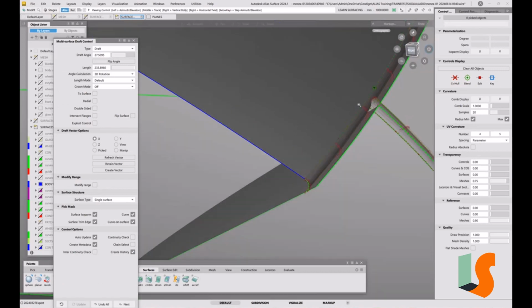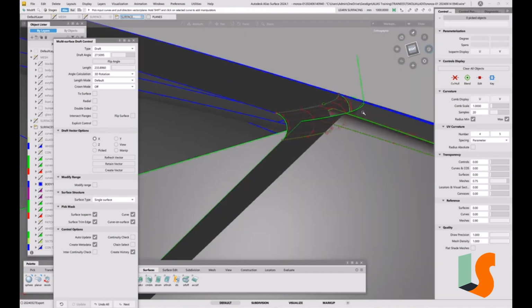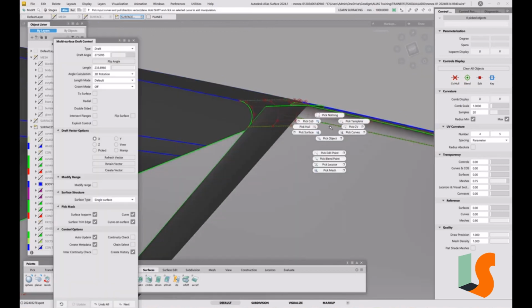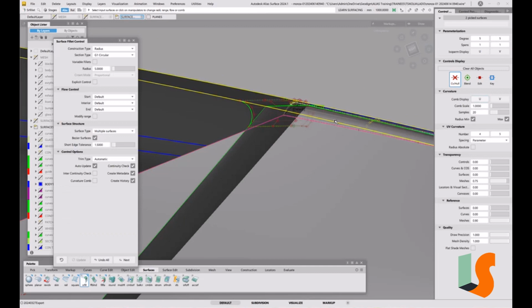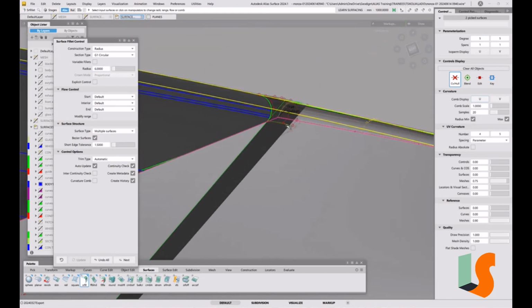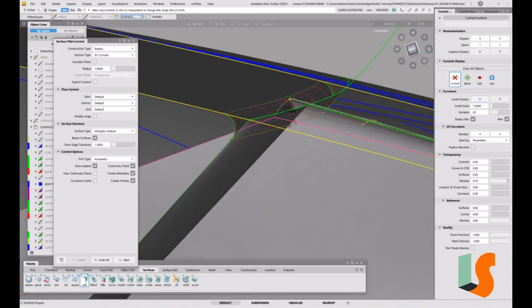It's actually giving us a more consistent feel to those two fillets. That's still 3mm, and that's a 5mm, which is quite surprising when you see that. You could increase the size of this fillet, of course. That would be another option, so that those edges don't have to be exactly the same. It's just that it'll make it easier to go from one to the other. So I've made that radius 7.